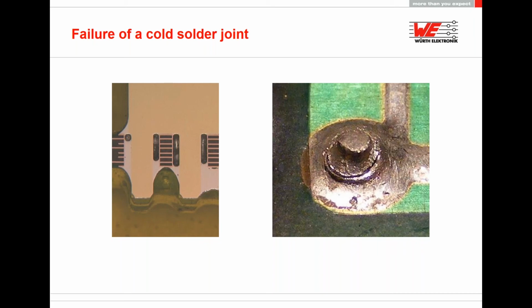And the easiest way to do it is starting with the cross section of the cable. For example, if you have 100 amps, you need a cable cross section of 16 square millimeters, for example.